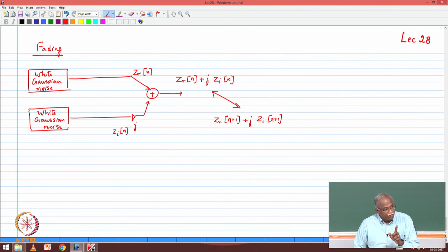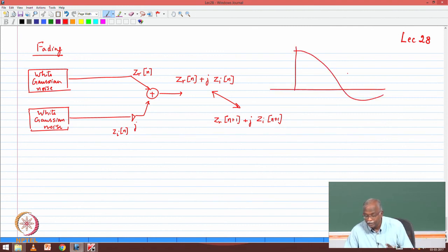But now, if I am in a fading environment, and I just moved my time observation by a few milliseconds, and you say the channel completely changed, no, that's not possible, because you know that the autocorrelation function is actually a Bessel function. Until you reach coherence time, the channel has to remain correlated, but this is totally uncorrelated.